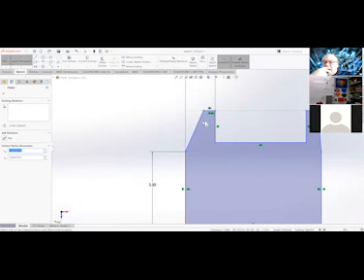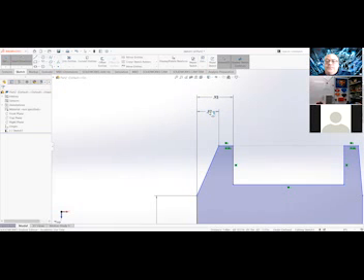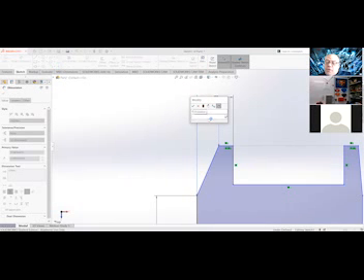Now, there's a couple things to watch with here. Because I'm doing points, that means I could do an aligned dimension. I don't want that, and I don't want this. See, as you move your cursor, it's going to determine where you're placing that value. I want it to come up and be in alignment with 0.933. So no, no, yes. Okay, and it's just where you put your cursor. Now, if I'm going up in the right direction, once I hit the left mouse button again, it wants the value. In this case, it's 0.69, and enter.